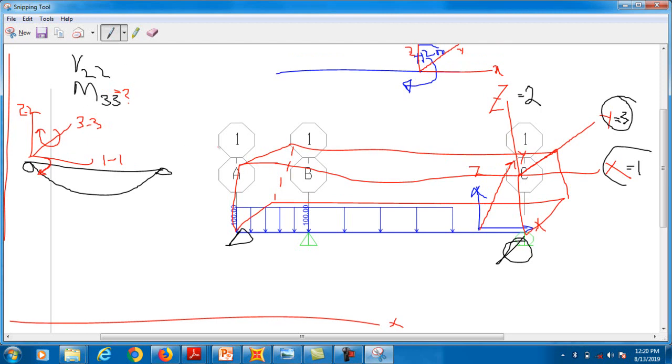But at this stage, whenever we are analyzing or designing 2D frames, 2D beams, 2D trusses, in all cases of 2D beam structures, you will calculate shear about 2-2 and moment about 3-3. This should be kept in mind. Clear? You must always remember that shear will be about 2-2 and moment about 3-3. Clear?